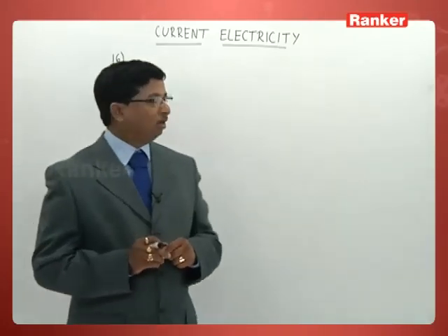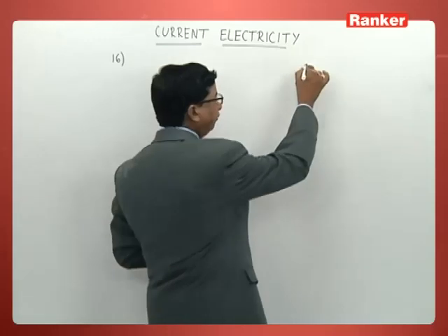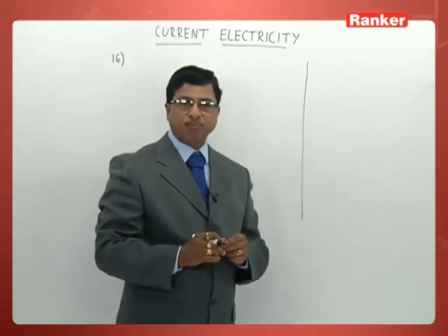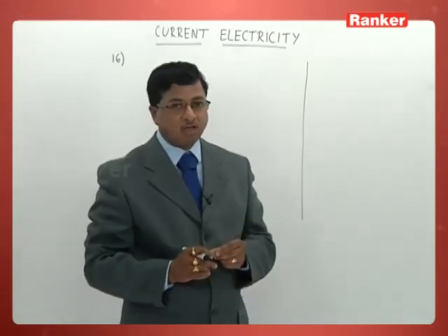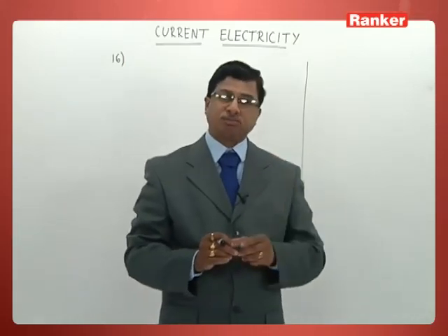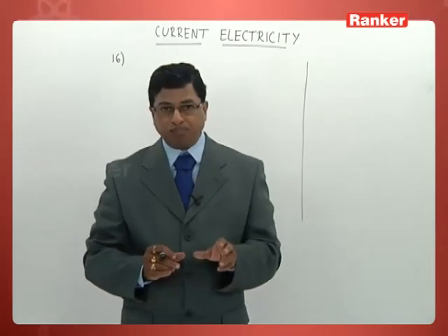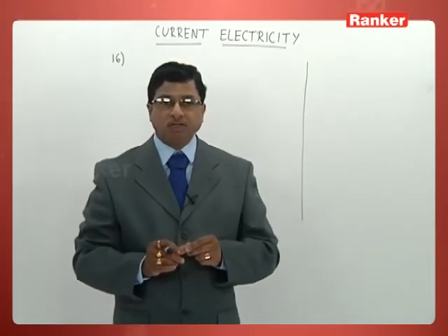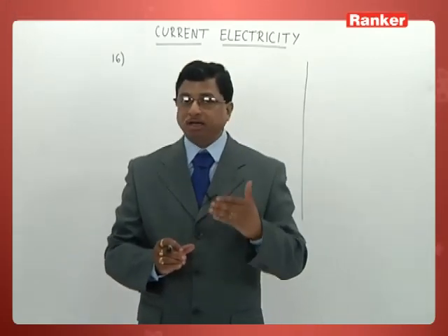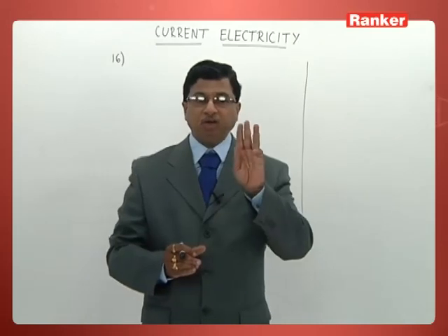He is just talking about a meter bridge here. Let me just remind you in brief what is the principle on which this meter bridge works. Every one of you knows it well. Meter bridge is a simplified form of Wheatstone bridge. I repeat, meter bridge is a simplified form of Wheatstone bridge. In Wheatstone bridge, to balance the bridge and to make the current across the galvanometer 0, you need to change 3 known resistances.